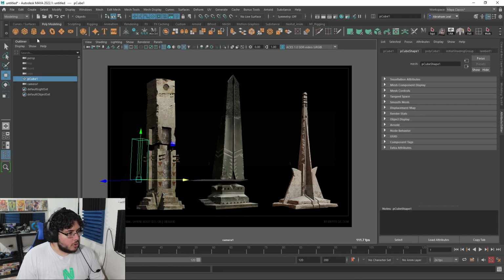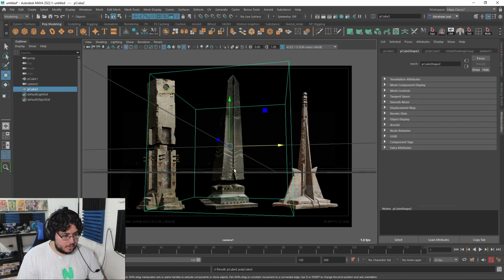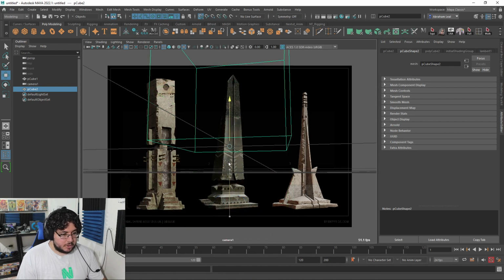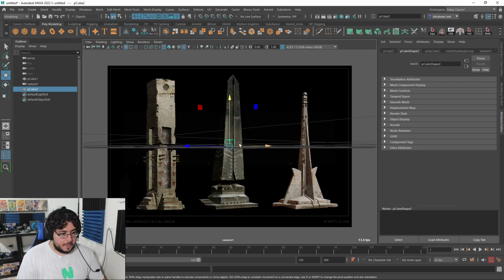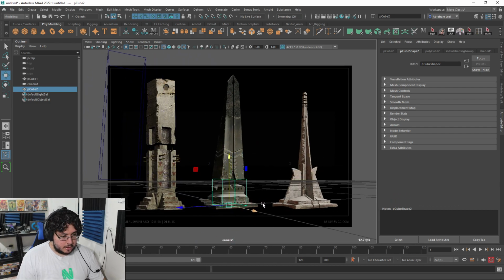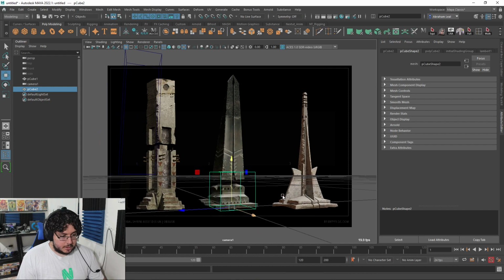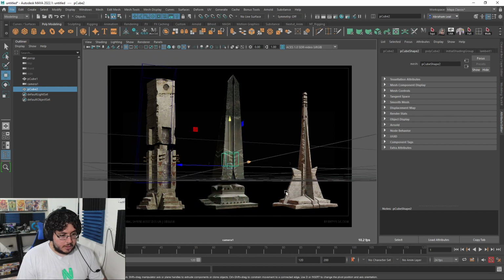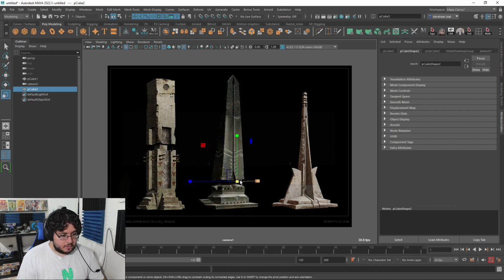And I'm just going to create a very basic cube. The one thing I'm going to do with the cubes, I'm going to move the pivot point with D and V to the base, and then with X, I'm going to snap it to the ground. And I'm going to try to match the perspective. I'm going to use the front part of the cube right here. Try to match the perspective here. So that's roughly the perspective. So I know, of course, this is going to be bigger. Just match the perspective as close as possible.